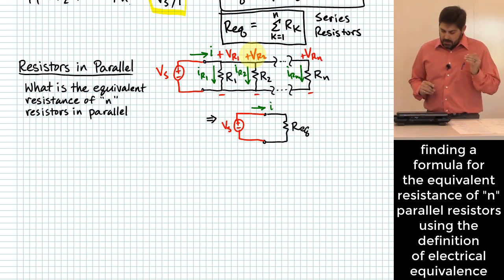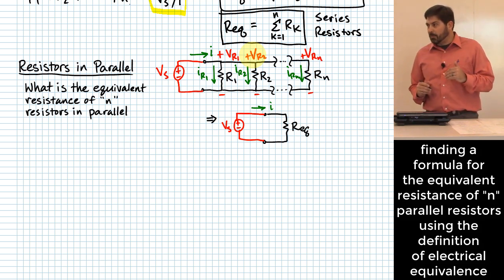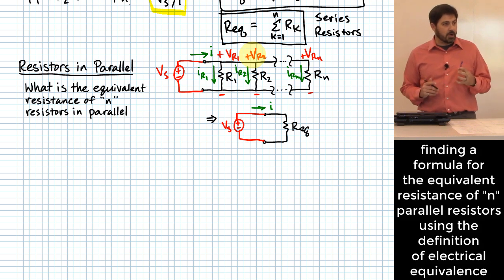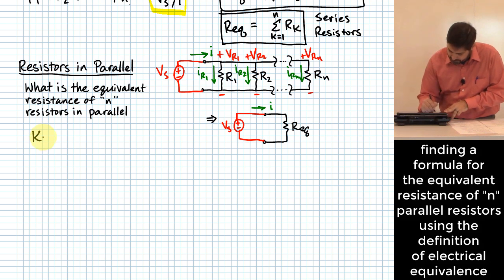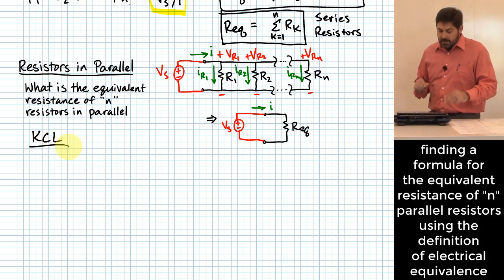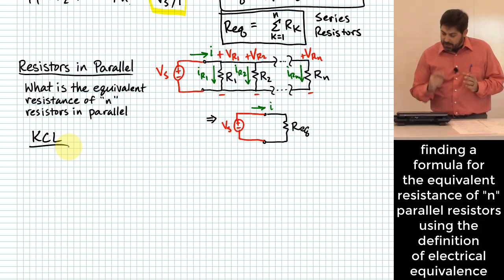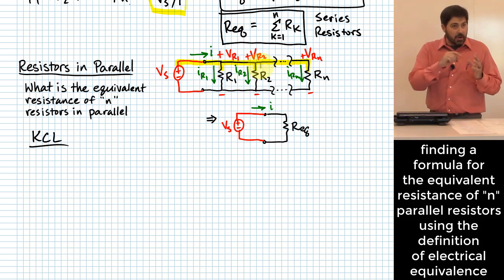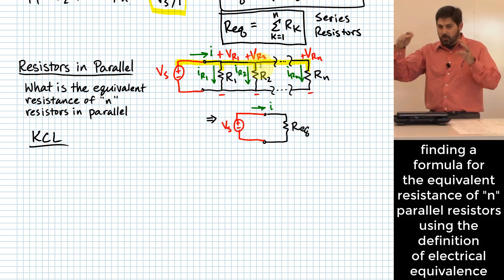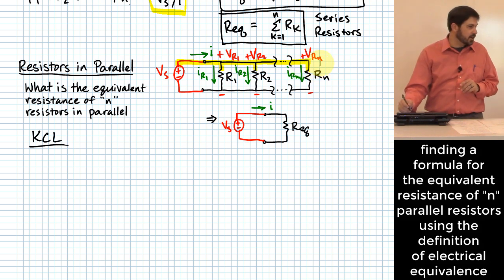All right. Now, in this case, probably the best thing to use in terms of one of Kirchhoff's laws is not Kirchhoff's voltage law, but rather Kirchhoff's current law. Let me label that right here, Kirchhoff's current law. What I want to do is see if we can identify a relationship for one of the nodes. Let's say we look at this node right up here. I know that's a node because I can highlight across that entire wire without crossing any of my circuit elements. I can keep on highlighting until I've got all of that drawn on, right?